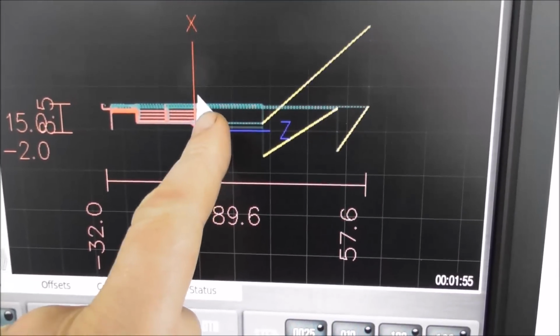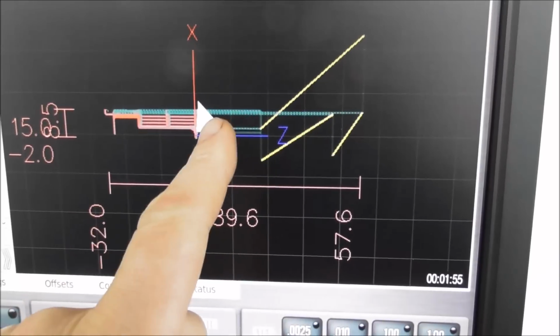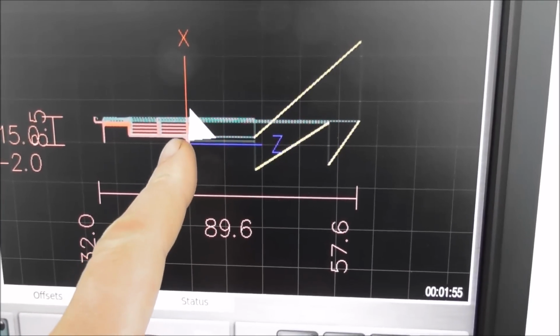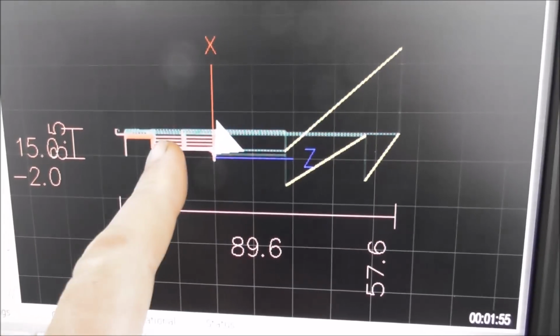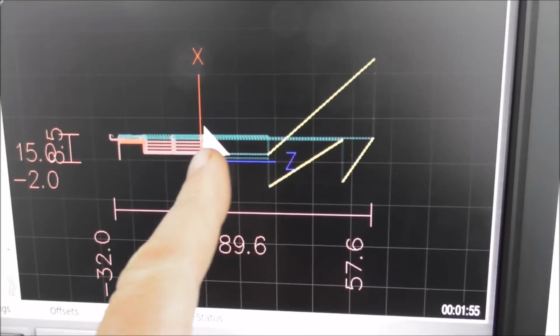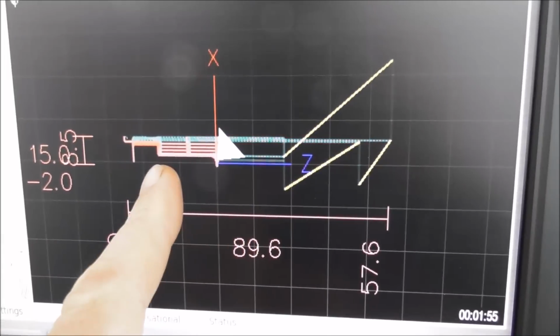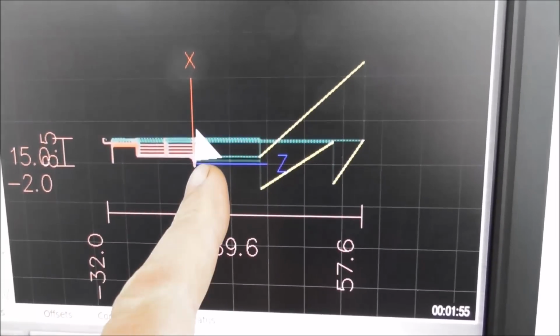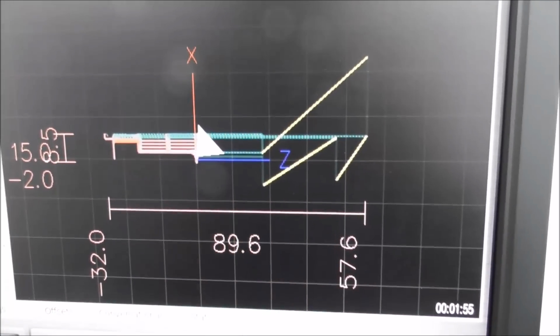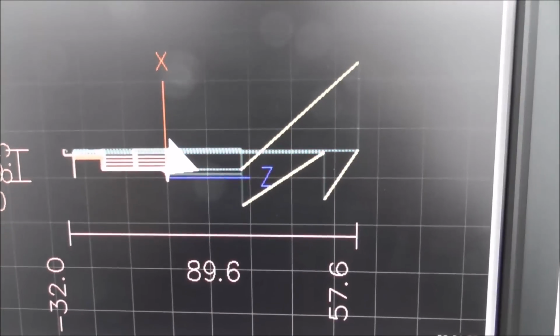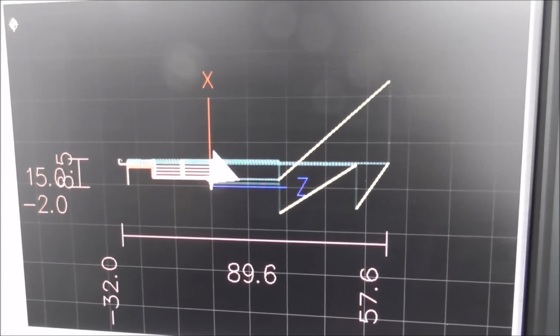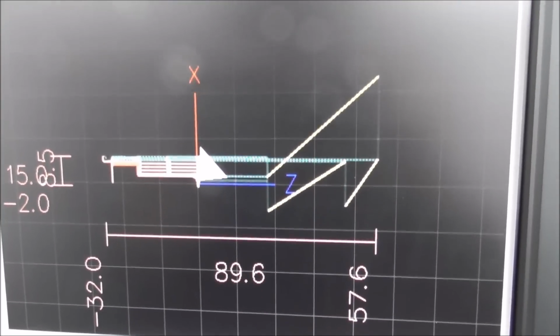That's my theory anyway. I'm roughing down that small diameter in 2 stages so that the small diameter is being supported by the stock and not roughing the full length, which would be too fragile for taking big cuts. Rather than getting effective chip breaking, because it's such a small fragile part, I can't take heavy cuts to break the chip.